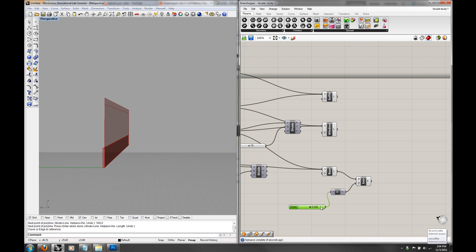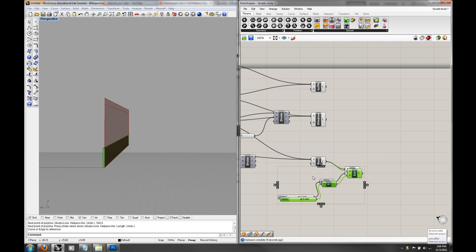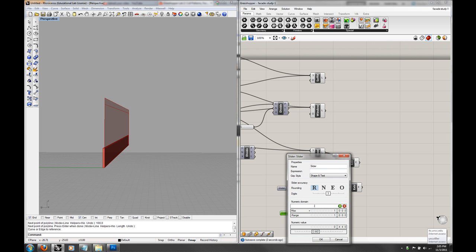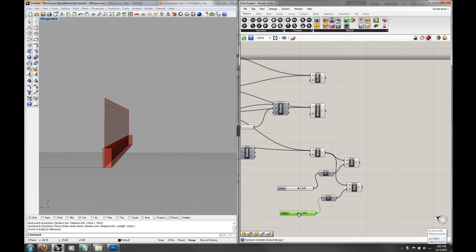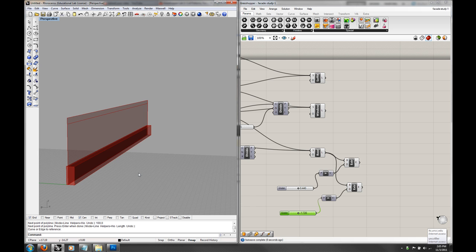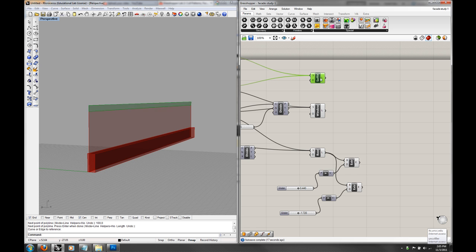We can do that, and then we can make a copy of all this, and we can make our slider negative, to -3 or something, and then we can make this go out. So I have two extrusions. I have one that's extruding this way and one that's extruding that way. There are other ways to do this, but this is just the easiest way with the fewest new things we have to introduce. And you could go ahead and apply that same logic to your soffit surface.